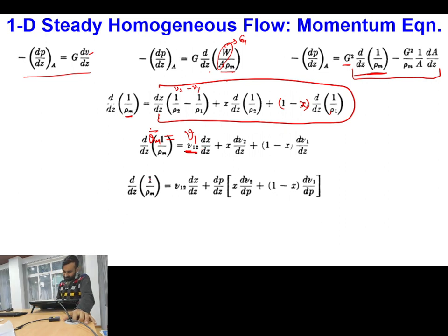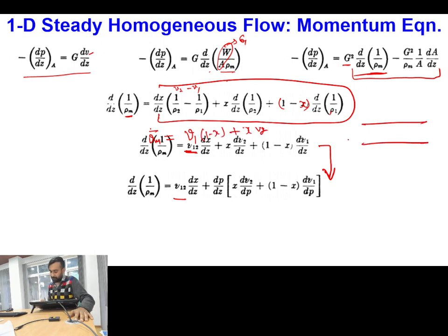So this further can also be written in terms of, okay, now from this step to this step there is one interesting fact. So in what scenarios do you expect that your mass fraction will change under the steady state conditions? If you have an adiabatic flow, in an adiabatic flow, if you are operating under steady state conditions, then within a pipe, if you are entering fluid 1 and then you are also entering fluid 2, if you call the conditions to be steady state, you have to keep the flow rate of fluid 1 and fluid 2 the same at each and every time.